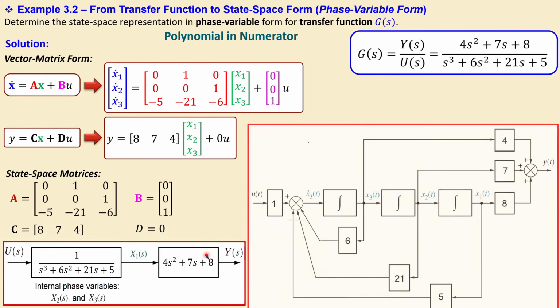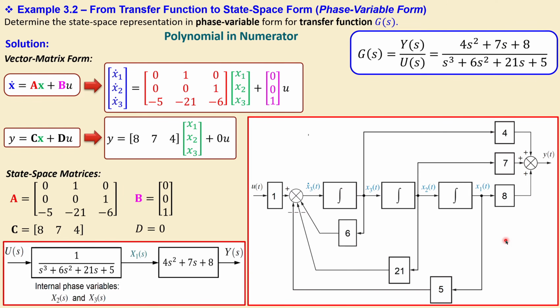And this is what we had, and this is now our diagram, our signal flow diagram. Remember that we had before this, and then we had the output there. Now the output needs to be taken after that x1. So x1 must be multiplied by 8, and then also y, but it also has to be differentiated, and then times 7. That's shown here. So from this to that, you integrate, but from this point to the left side, you go in differentiation. So differentiate that, and then you multiply by 7, and you get the output.